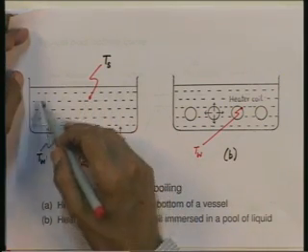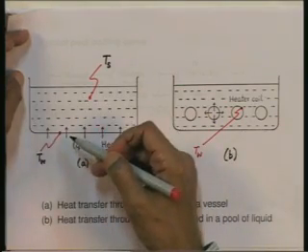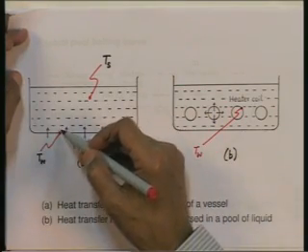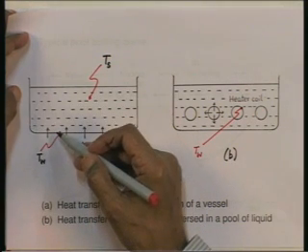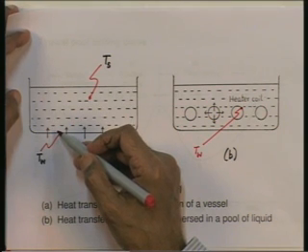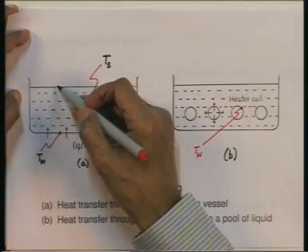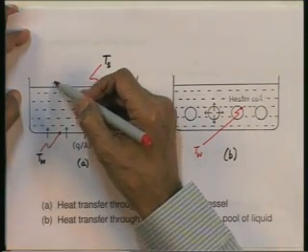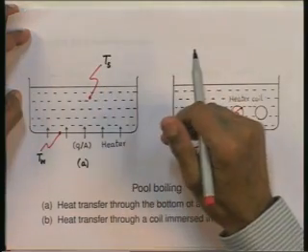A natural convection current is set up inside this pool of liquid, because the liquid at the bottom gets superheated, goes a little above T S by a degree or half a degree more. Its density decreases, so it rises. So, the heated liquid rises, comes to the surface, and a little evaporation takes place from the surface.